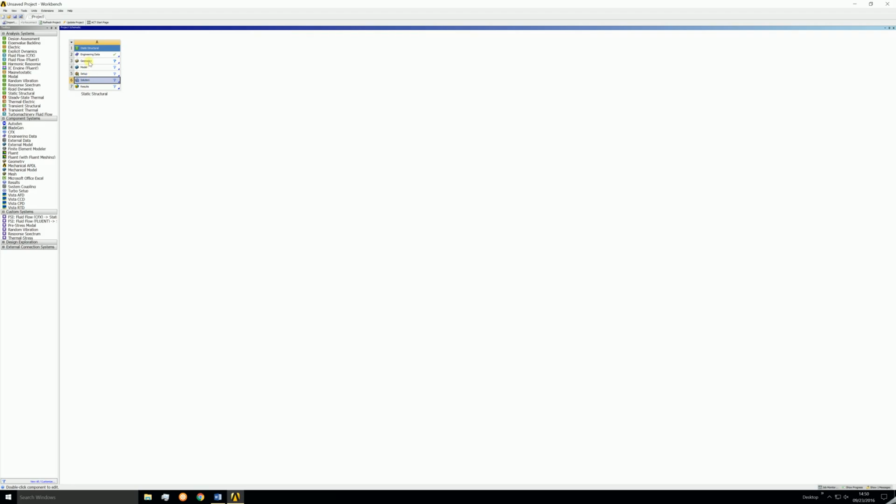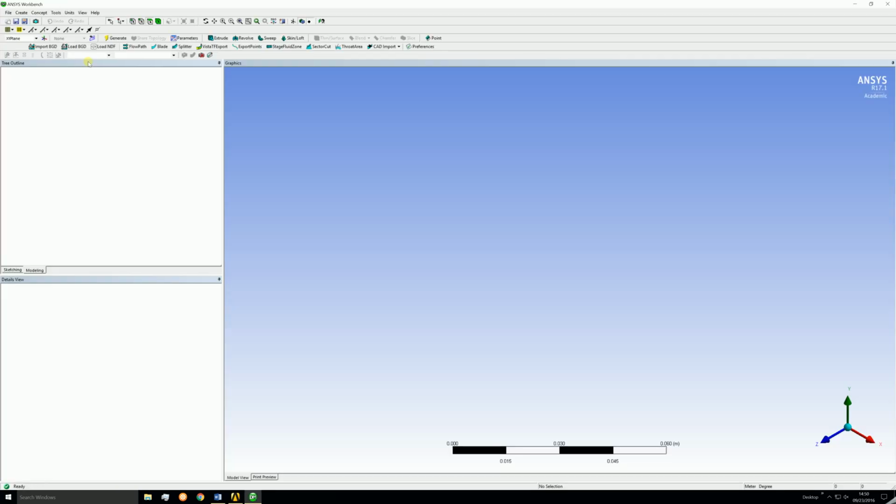We'll start by creating the geometry, which is done by double-clicking the Geometry section to launch Design Modeler. Design Modeler is the CAD program within ANSYS that we use to edit geometry. When it's open, you'll see a big blue window and a tab with 3 planes, XY, ZX, and YZ. Those are the base planes for our standard XYZ coordinate system.